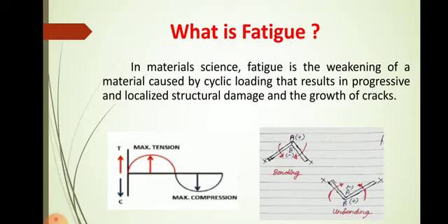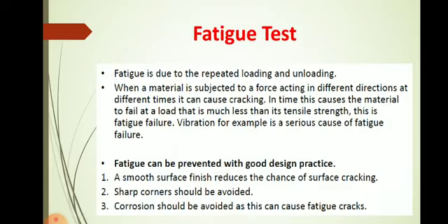For that purpose you are applying continuously cyclic load. Here one cycle for that load is shown. You are applying the tensile load as well as compression load in a cyclic manner. Similar cycles will follow further along the span. With the help of this fatigue test, we are finding the endurance limit, below which the number of cycles or cyclic loads that the material can handle will be more. So for finding that endurance limit, we need to carry out this fatigue test.